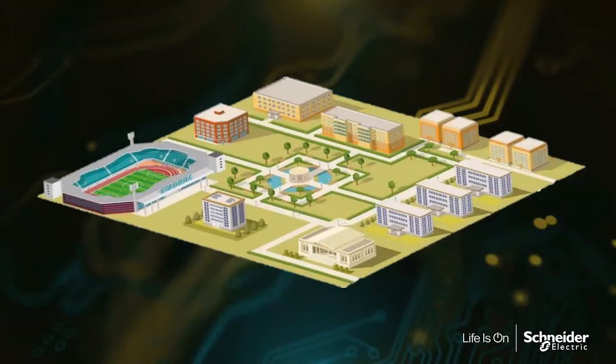And you may wonder how these power quality issues come about. These are particularly prevalent in modern society because of the increase of LED lighting and variable speed drives. And these, although they are great for sustainability and it is highly recommended to use them instead of incandescent lighting, for example, they are active loads rather than passive loads, which means they contain a lot of diodes and transistors, which will put harmonics on the system and also damage the power factor.